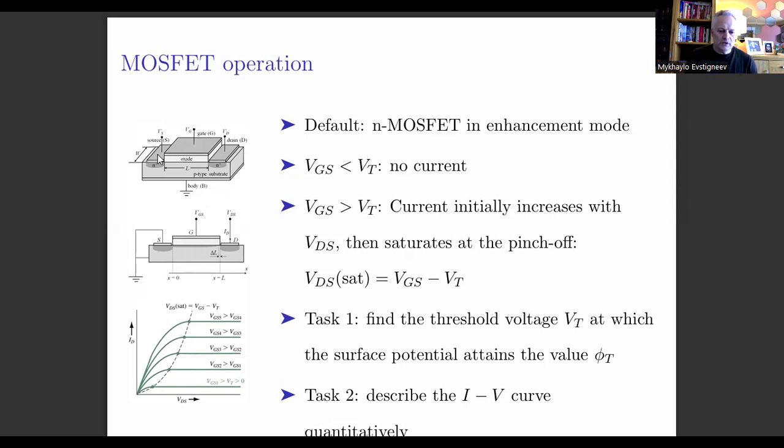Then you have two electrodes, one here and one here, which are called the source and the drain. These two electrodes are really just heavily doped N regions inside this p-type body. So you have a heavily doped N region here, the source, heavily doped N region here, the drain, and of course you have some metal plates or something attached to those N regions, so you can control the potential applied to the source and the drain. You can collect the current flowing.